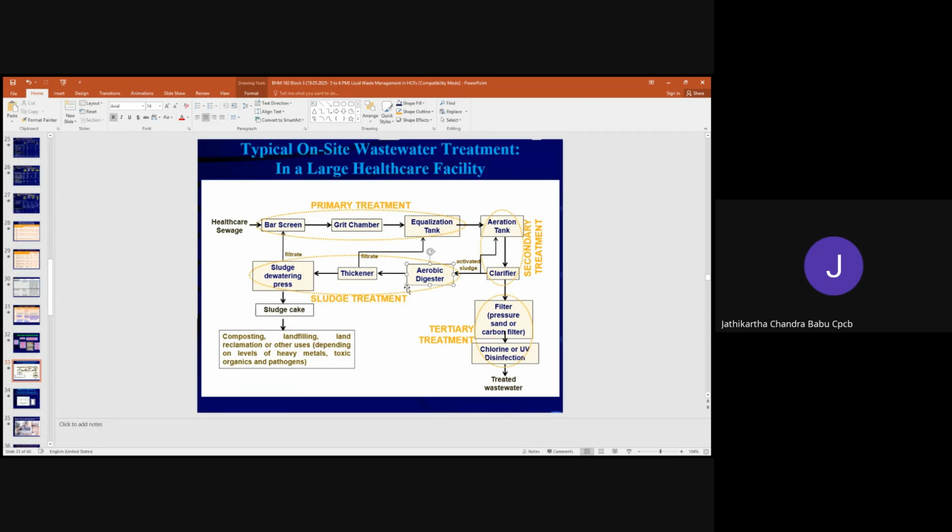The sludge is called activated sludge. Some quantity is always recirculated to the aeration tank in order to maintain proper biological activity within the aeration tank, and the excess activated sludge is removed. Whatever waste is received, the ETP sludge from the clarifiers, is collected here. It will go to the digester, followed by the thickener.